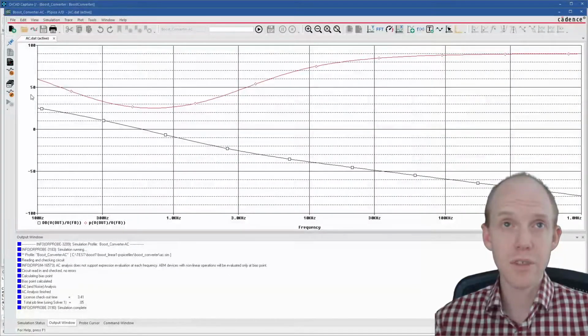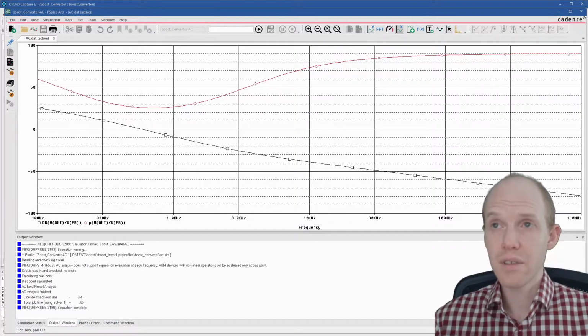So there, that looks more like a Bode plot. So we have the gain starting at positive here and crossing down over 0. So this is the gain bandwidth right here. It's pretty low. It's below a kilohertz, and then the phase is going off over here. The phase should cross down over 0, and we're not really seeing that. That's probably because it's such a simple circuit and we don't have a realistic op amp. We can try adding a couple things to make it a little bit better on the phase.